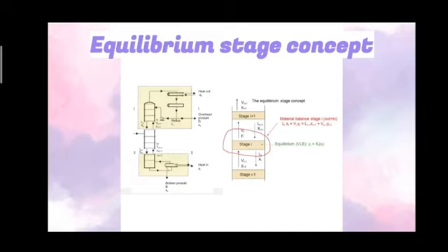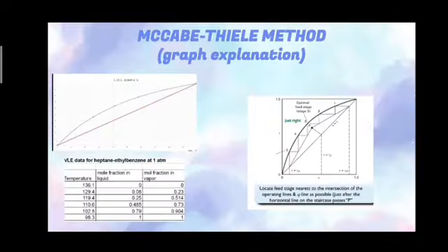So the material balance for the stage is L_i x_i plus V_i y_i equal to L_(i+1) x_(i+1) plus V_(i-1) y_(i-1). But to calculate for the whole tray, using these stage-by-stage calculations is time consuming and often unnecessary. So one of the quick methods of estimation for the number of plates and feed stage can be obtained from the graph of the McCabe-Thiele method. First, I'll be explaining the graph.